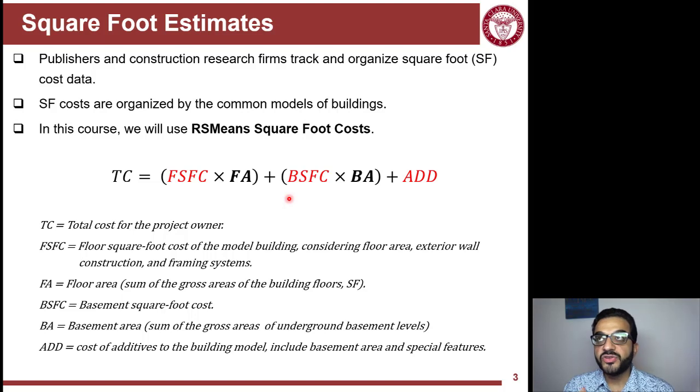The decision to have a basement or not is also a very strategic decision at the beginning of the project. So you need to split having a basement from how many floors you will have above ground. The first term here is the gross floor area, FA. You multiply the floors by the square foot of every floor, and you get the total floor area of the building.